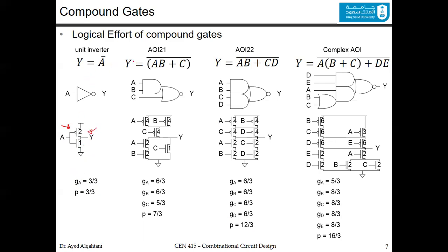So let's do it for the other one, where you have AB or C, all barred. This is a logic circuit for it, and actually this is a compound gate. You do this by having AB in series. Now you have the whole bar here. So we take whatever is under the bar, and we design it in the pull-down network. So you have A and B in series and parallel with C, as you can see here.